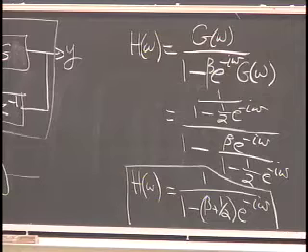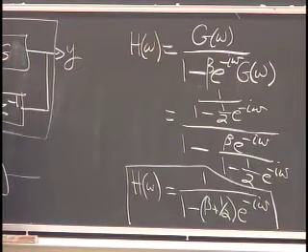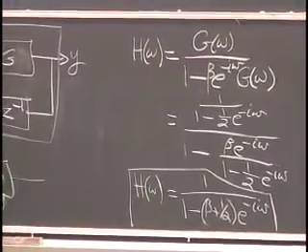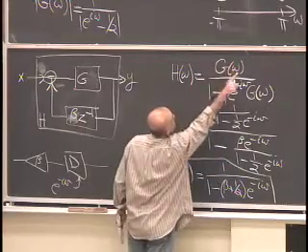-1 to 1. Right? I don't want to go outside the unit circle for reasons that you wouldn't know at this point. Well, actually, you would. The reason that x doesn't go outside the unit circle is that if you have a number larger than 1, when you plug that into the frequency response infinite sum, it's going to blow up. So that's why I want that exponential to always stay within the unit circle. And if it's real valued, that means it's got to be between -1 and 1. So this beta, subject to that constraint, enables me to move that x from +1 to -1.